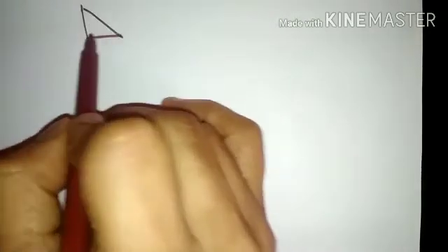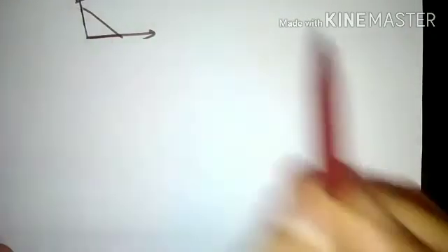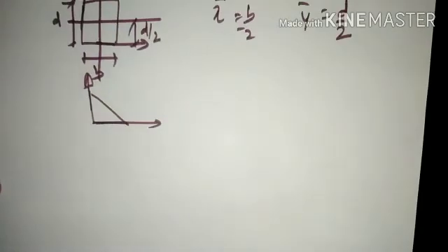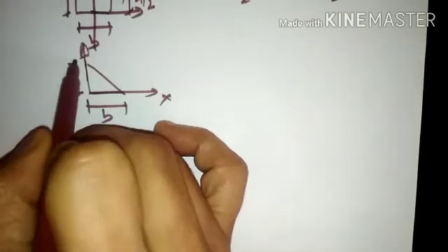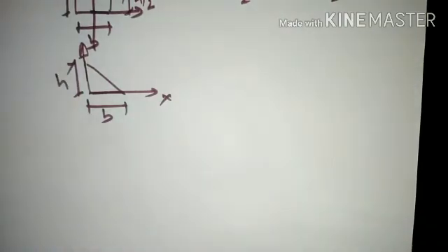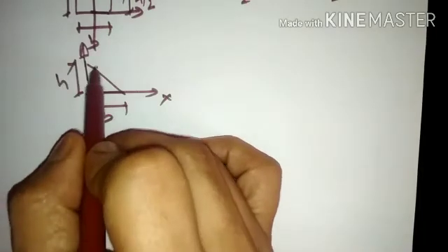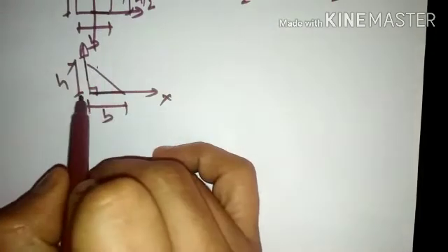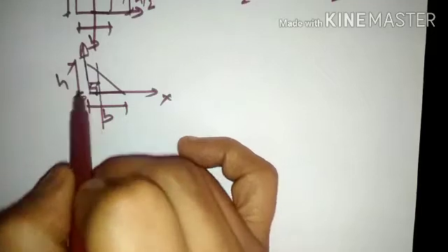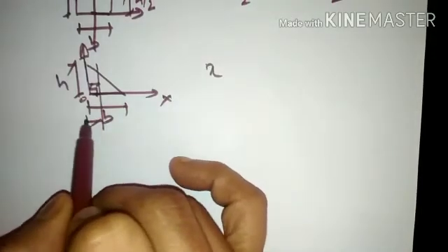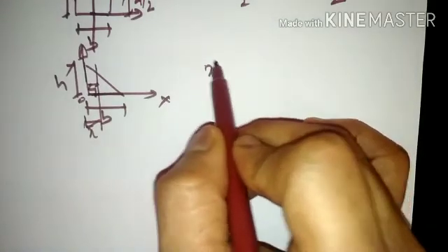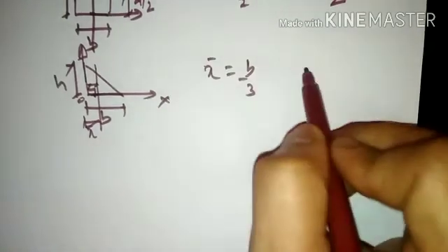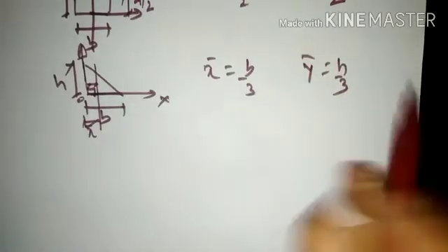Likewise, after the rectangular section, we had considered a right angle triangle and we did the derivation for both along x and y direction, placed in the first quadrant, and the base distance is again b and height of the triangle is h. Now the center of this particular triangle with respect to the 90 degrees angle or with respect to the origin here, it is at a distance of x bar, that is this particular distance from the origin proceeding along the x direction or along the horizontal direction. x bar would be b by 3 and y bar would be h by 3.